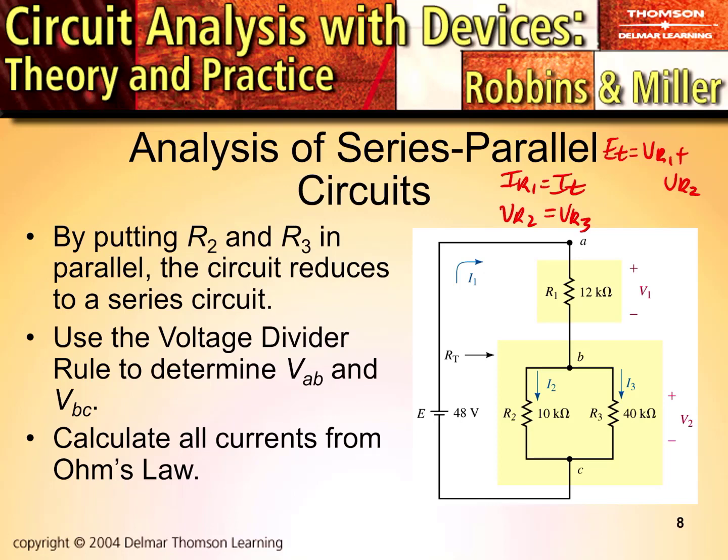Okay, so let's take a look at this circuit then, and let's start by determining what our R total expression is, because that's going to be our next step. It's already redrawn in the manner of which we would use to analyze it. So that being the case, then we can say that our R total equation is R2 in parallel with R3 then added to R1. Notice how we packed up that R2, R3 connection, and then we're going to add it to R1.